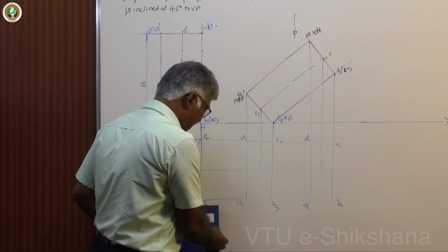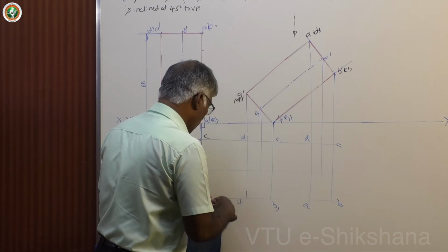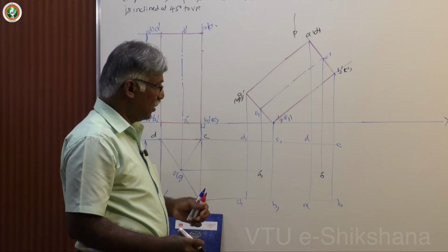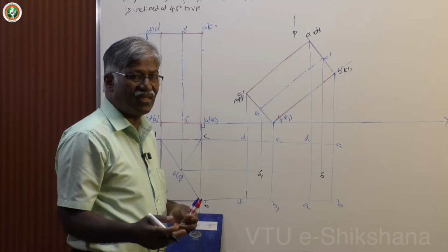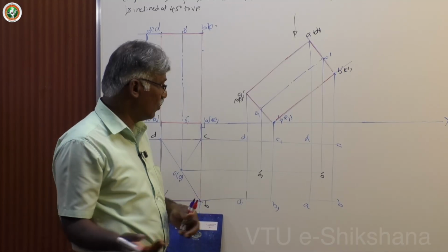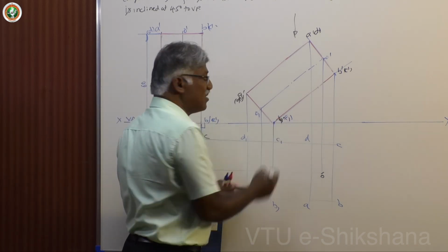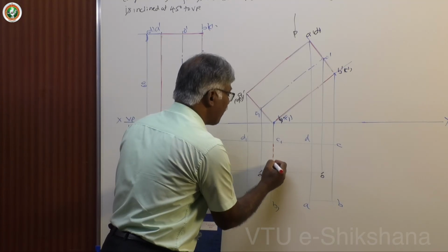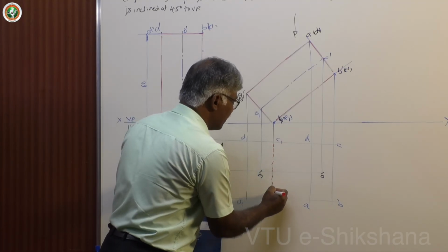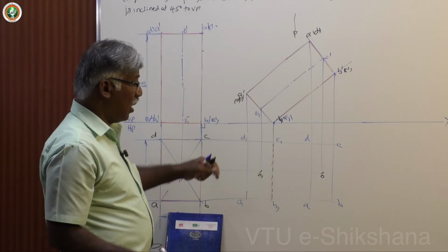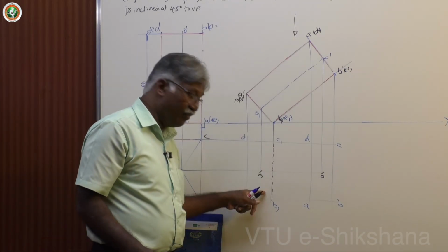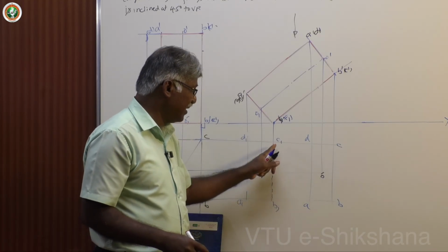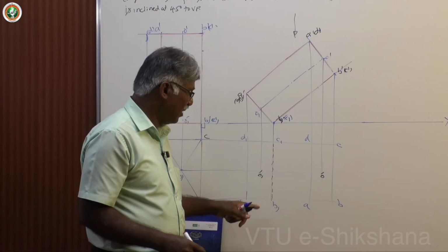visibility concept. Assume that I have drawn all with light lines. This is O1, O. Now, if you are here, first method, easiest method is the farthest item from you. Which is the farthest item from you? B1, C1. So, B1, C1 is not visible. Draw dotted line. That's all. Any number of lines connecting to this item are not visible. Let us analyze. Here, this particular line C1D, C1C, all these are connecting to B and C.